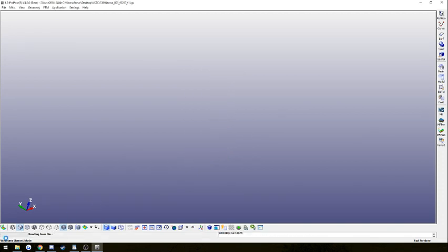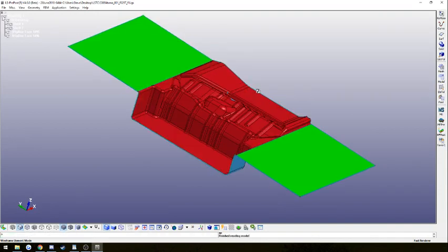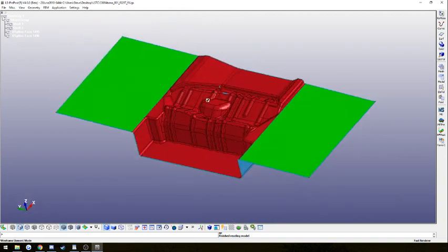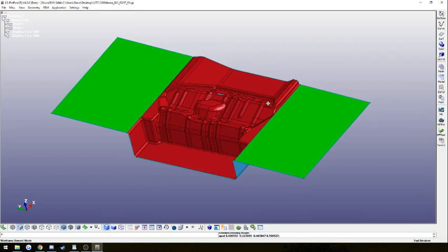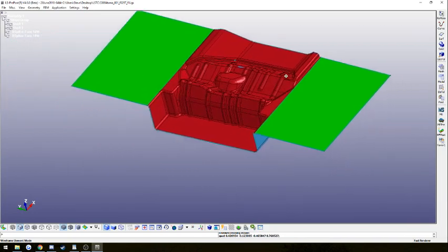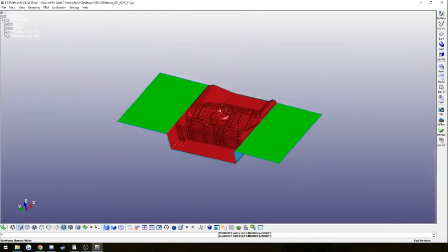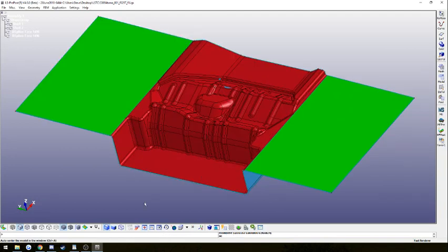Once we do that, we'll see this loading bar in the bottom left fill several times to assure us it's actually working. Once we import the file, we're going to go over several movement options so that you can tell everything's all right and get yourself comfortable. We can hold Control and click to rotate the object. We can hold Control and use the middle mouse button to drag the object, translate it around. And we can hold Control and use the scroll wheel to zoom in and out on the object. We can also use this in the bottom left, or middle bottom left, to auto-center the object, which we can also do through Control A.